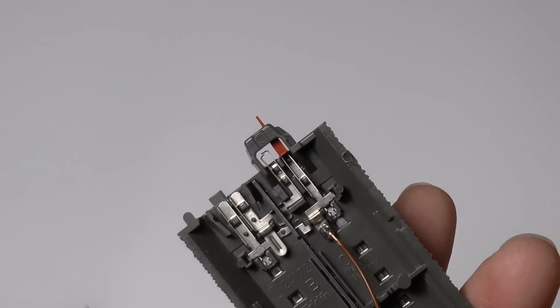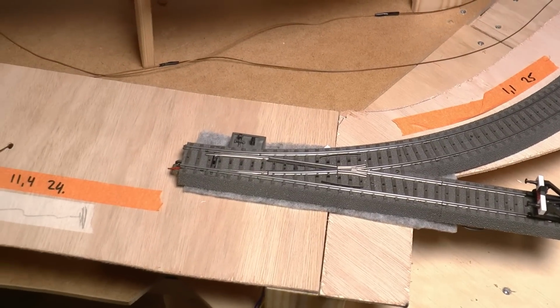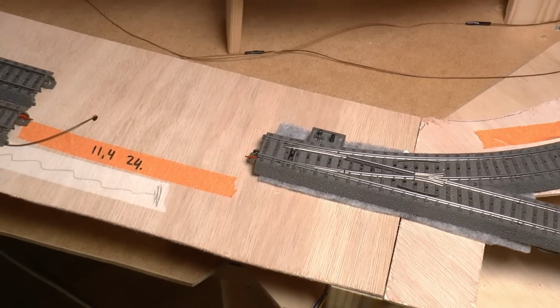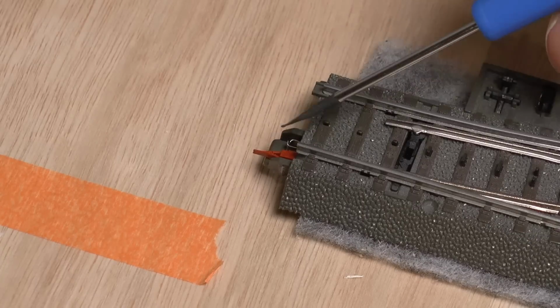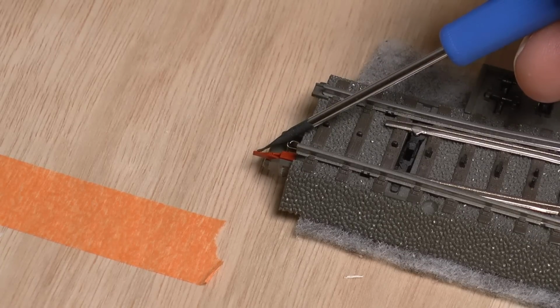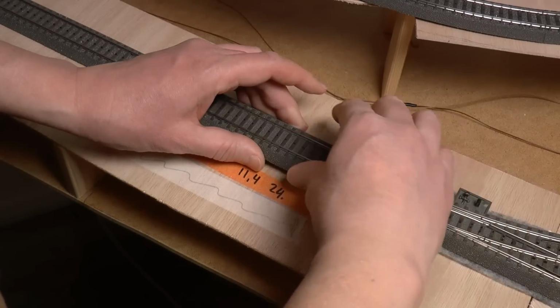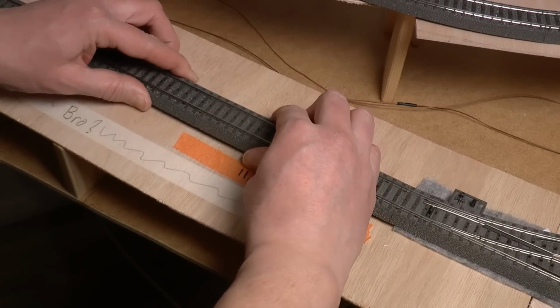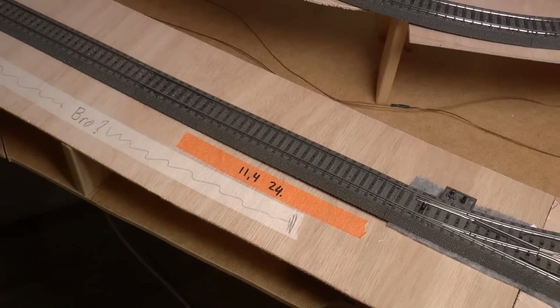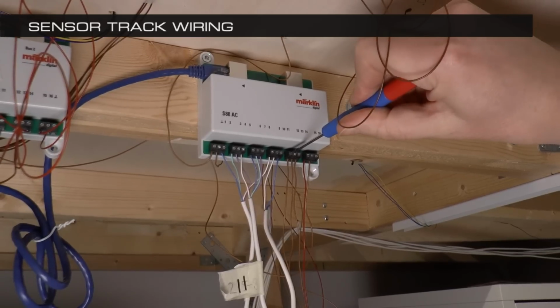So here are the isolators now assembled, as well as the cable. So let's insert this now into our piece of layout. And as you see here, I've marked the position of the sensor tracks with an orange tape together with the address for it. So I have inserted an isolator here in this turnout, and now let's assemble this track piece here, which holds our sensor. And with that done, we can now connect it to the feedback decoder, depending on what type of feedback. I'm using the S88 from Marklin here.